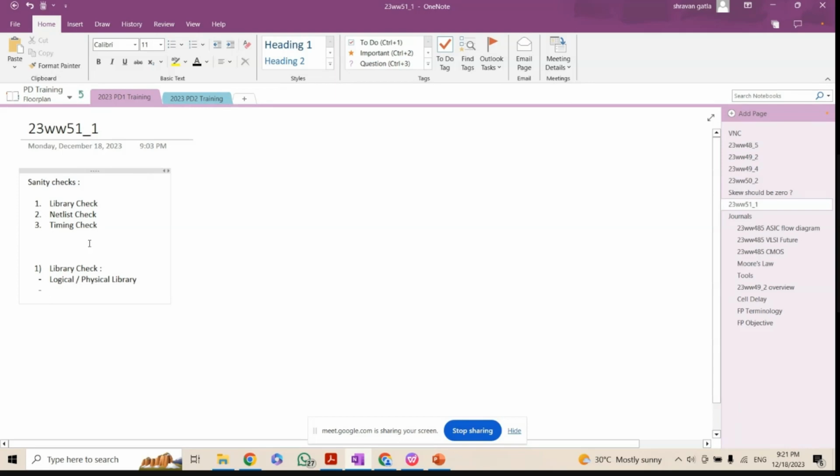So we will try to route them in the top metal layers, maybe M14, M15, which have less delay, because the width will be more, right? We have seen in the dot LEF file that the width of the metals is changing. So we use those big premium metal layers, and if it is fixed, good. Then you will go to this step again.